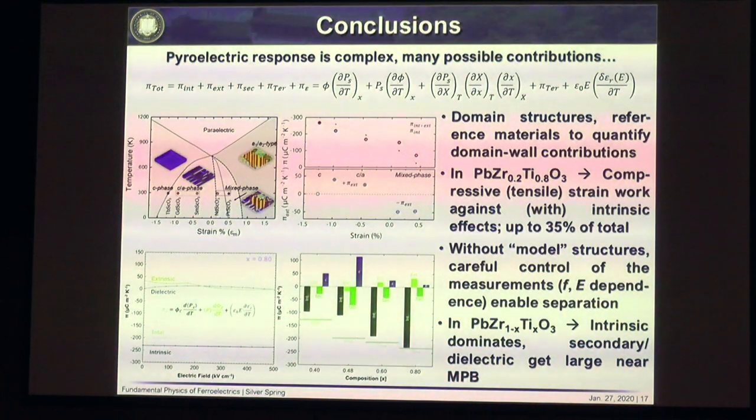And the other polarization that you monitor is simply the spontaneous polarization or the remanent polarization in the loop that you calculate? That's a good question. We've actually done the measurements both ways. Many of the things that I've shown you for these loops are almost quasi-static. They're very slow types of measurements, so you should think of that as being almost at remanence in these systems. We have tried to do faster measurements. It cuts down on the accuracy of our pyroelectric and electrocaloric measurements to do these things faster, but it's a balance. If you wanted to do that, I think we can think about ways of doing those experiments. Both on field and at remanence is relatively easy. On field is a little harder. It's a good question, though.